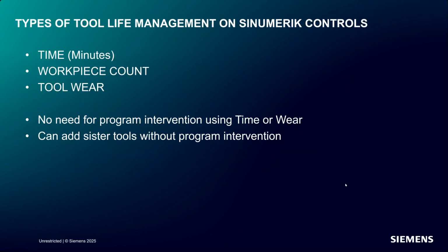Because in the medical device industry, if a program is approved and certified and I make any change to that program, like adding M codes, I have to switch it from approved to not approved, which means they can't run production until the machine is set up, I run a first article, send it to quality, and they inspect it and sign off on it. Now I can change it to approved and we can run production, which typically meant at least a day of being down. So when you have to do that 700 times, that can be a big problem.